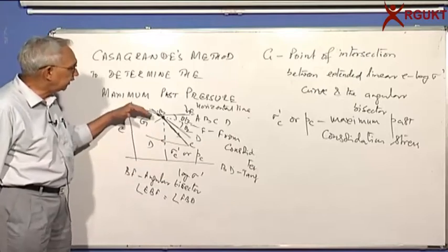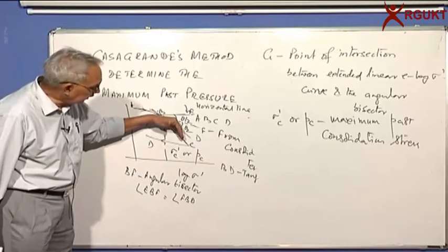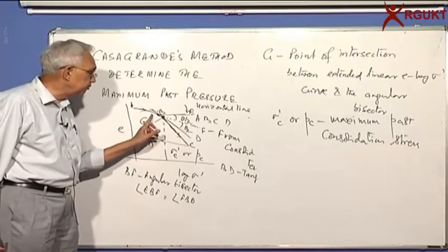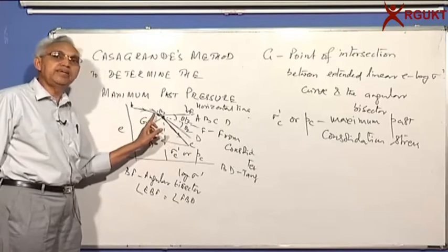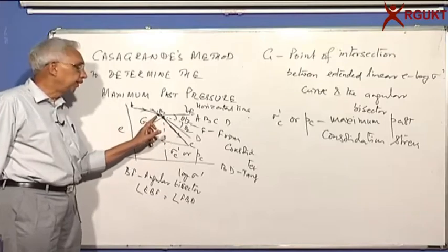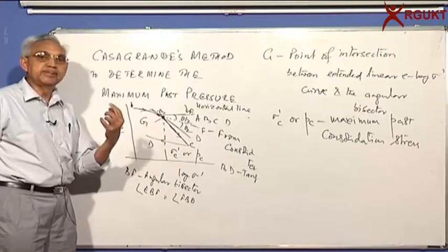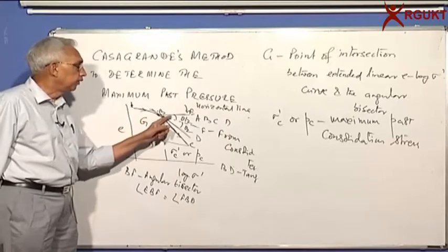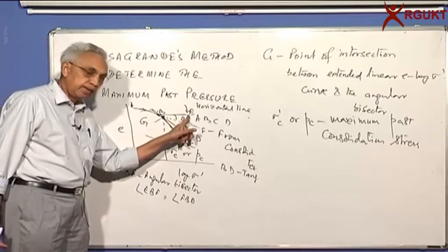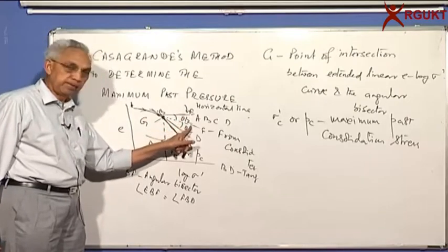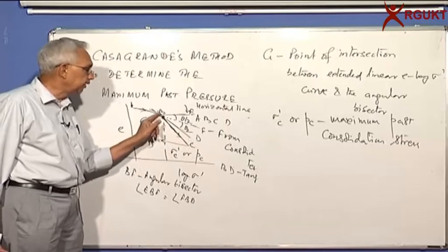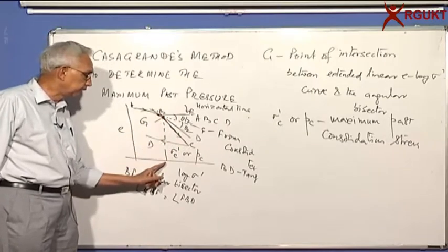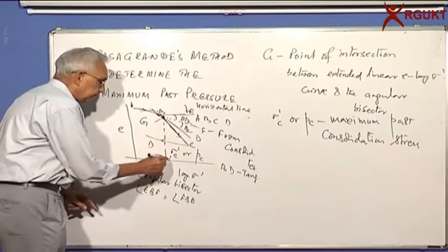Initially the curve is flat, later also it is linear, but in between it changes shape very sharply. You pick up the point of maximum curvature, which means the smallest radius. At that point, draw a tangent. You also draw a horizontal line and divide the two to get the angular bisector. Extend the linear portion back, and where you find the intersection, that corresponds to the maximum past consolidation pressure.